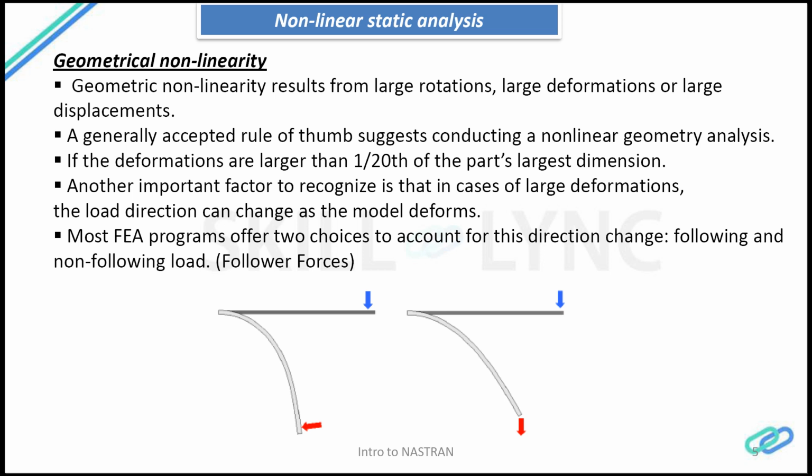In geometric nonlinear analysis, another important factor is to recognize that in cases of large deformation, the load direction can change as the model deforms. So you see here it is vertical, but over here it is almost parallel. So the direction of the load changes along with the structure.